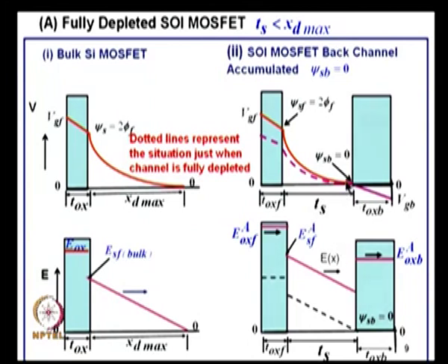So, the distribution now will be this potential is 0 here. Why? There are plus charges here with very small potential here, that is, the accumulation layer is still maintained. So long as there are plus charges here, accumulated charges are there. Where are the plus charges coming from? They are accumulated. So long as plus charges are present, the potential is 0. If I go on increasing that, if the plus charges disappear, then it will start depleting, but there are plus charges at 0. So, from here to here, what is the potential here? We are considering the situation where it is inverted, twice phi f.